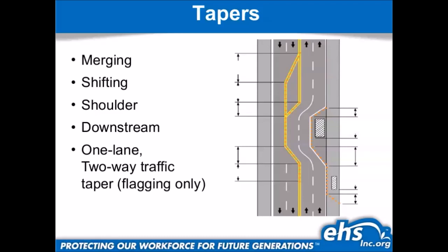So you're saying, hey, I know we shifted these lanes over this way. Now we're putting them back into their normal position. If you closed out a lane, this taper will also say, beyond this point, we're opening this lane back open for use. So again, this just returns things to the normal placement, normal width, normal position, and again, opens up those closed up lanes. Flagger taper is a little bit harder to explain, and it involves 2 opposite flowing lanes.